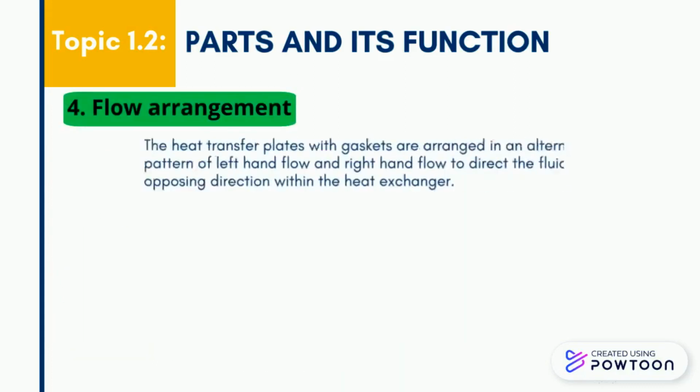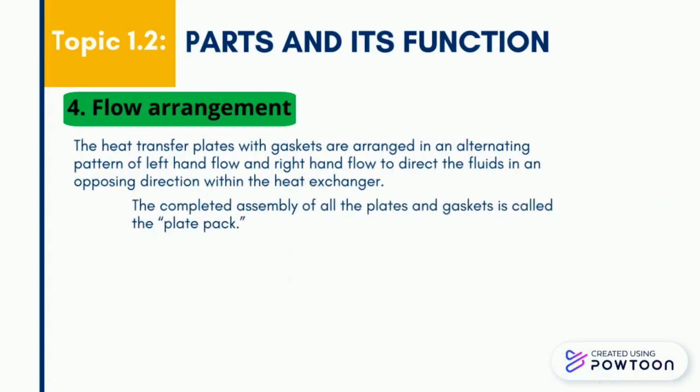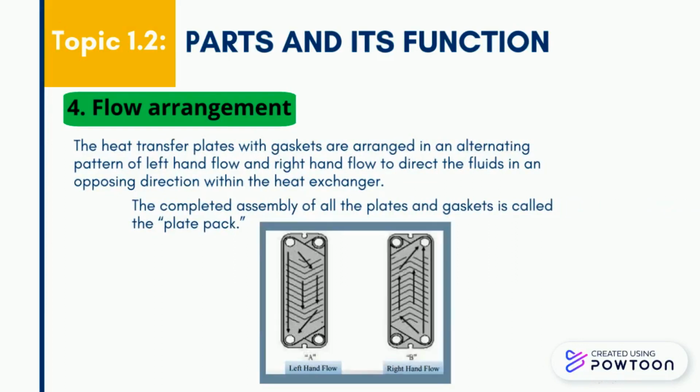4. Flow arrangement. The heat transfer plates with gasket are arranged in an alternating pattern of left-hand flow and right-hand flow to direct the fluids in an opposing direction within the heat exchanger. The complete assembly of all the plates and gasket is called the plate pack.